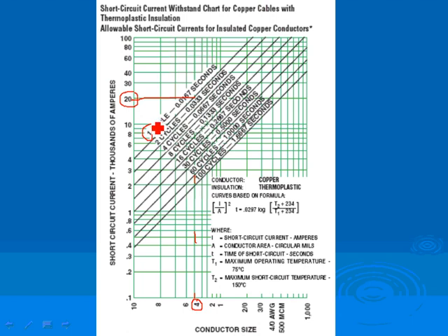Now suppose I have a switchgear and I can turn this circuit breaker, dial it. Can you guys see that dial? When you dial the circuit breaker, you delay the tripping of your circuit breaker up to 30 cycles. Up to 30 cycles, then this will continue. Is that 30 cycles? So that's curve 1, 2, 3. That should be right here, right? Oops, right here. Okay, now that's it right here. So that's my 30 cycles.